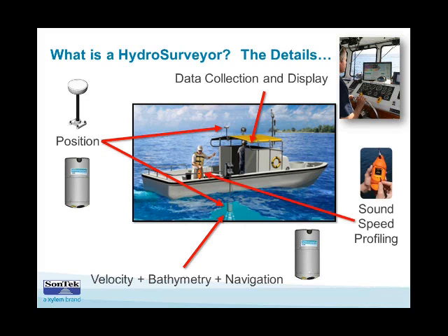And then data collection and display via the HydroSurveyor software, and also real-time navigation of the boat for hydrographic surveys. And lastly, we have the optional CastAway CTD, which is needed for sound speed correction if you're using acoustics to map bathymetry. The advantage of using the CTD over another sound speed profiler is that it's fully integrated with the HydroSurveyor software.